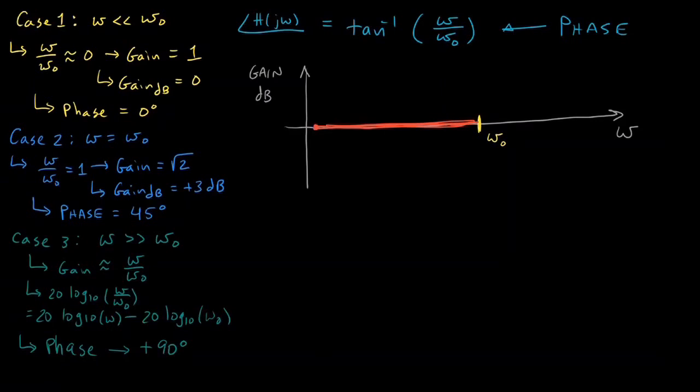Well, if you recall, a 0 at the origin always crosses through 1 radian per second. It turns out if you move the curve down by this value here, negative 20 times the log base 10 of omega naught, it will slide that over so it crosses at omega naught radians per second instead of 1 radian per second. So our straight line will then increase at 20 dB per decade off in this direction. Okay, so that's our straight line approximation.